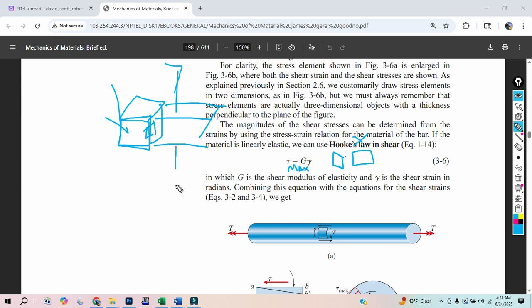And if we apply any force at all, we for sure get a slight angle. We get a diamond shape no matter how much shear force we apply. The other thing is if I'm applying an upward and downward force, that creates a moment this way. So I need my 2 other arrows that way and that way. And just the fact that I'm shearing something, if I'm pushing up and down with what I would register as known forces, yeah, those sound like the forces that are shearing. It's bizarre that there's an equal force sideways to keep that thing from rotating.